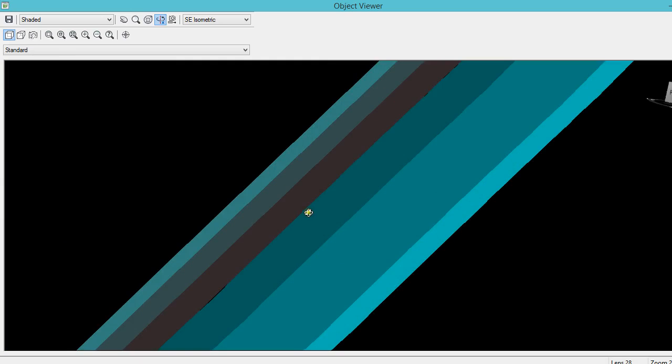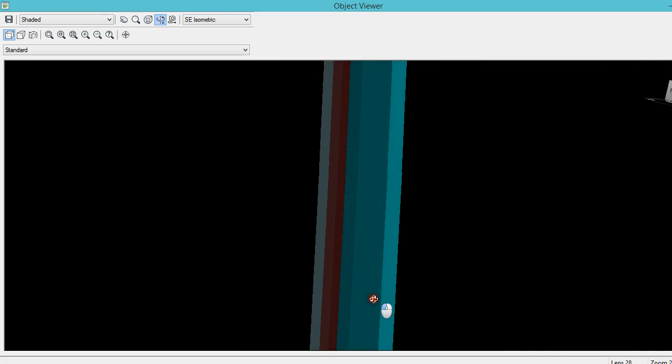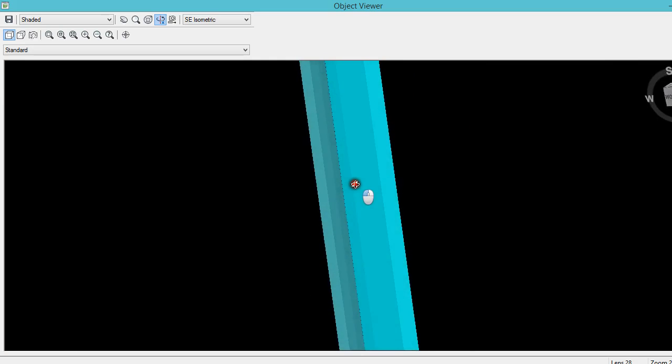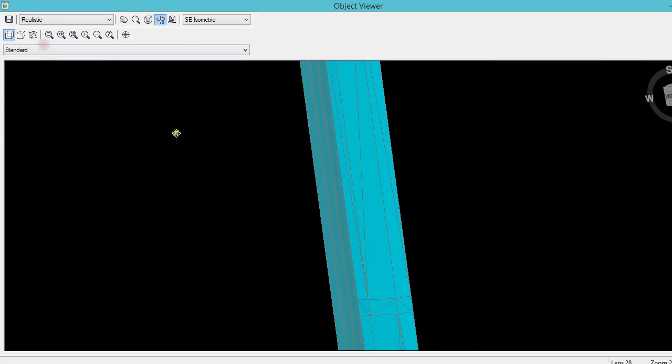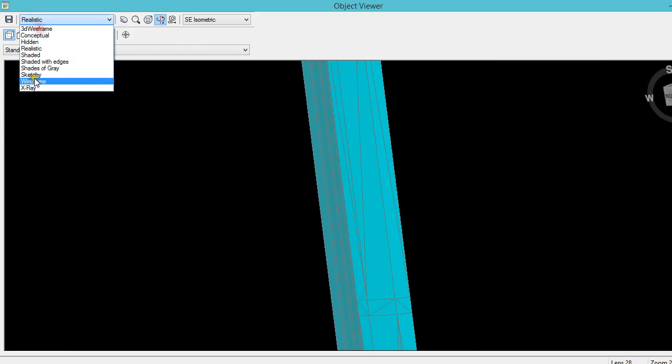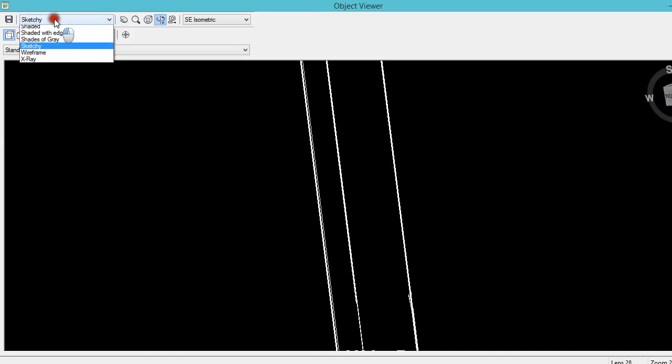So what we did, we created a feature line on the channel, the 0.45 down, and here we raised it, offset it, again offset, and lowered it down. So we have that channel shape ready. You can see now it's a bit clearer, different shapes.